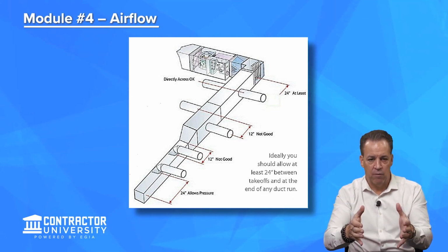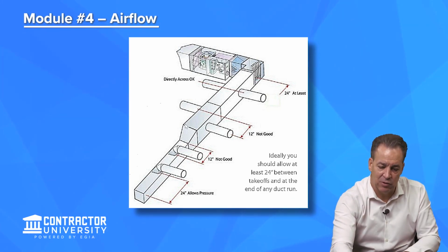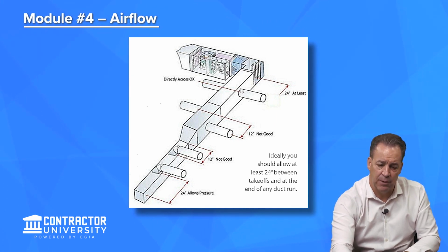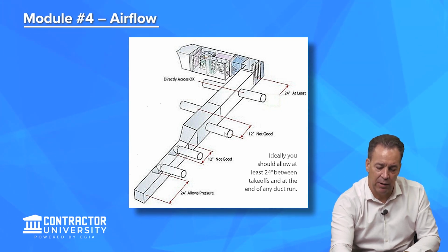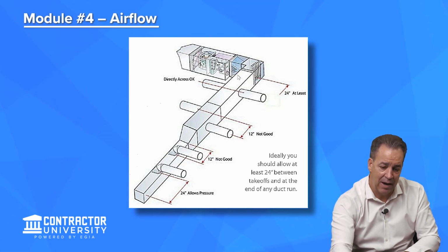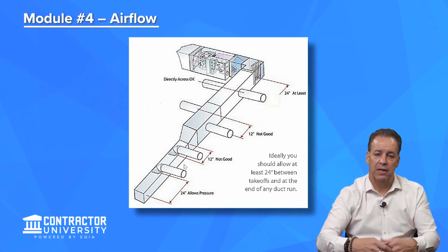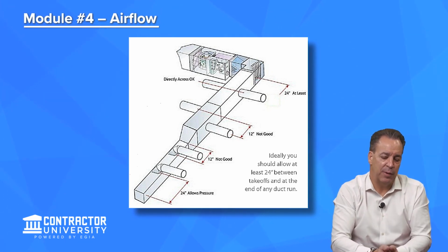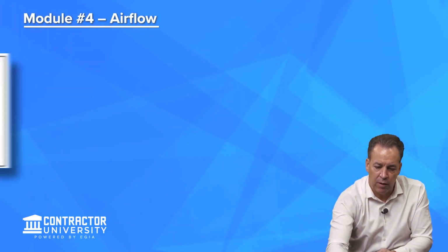We shrink the ductwork for the amount of air that's now left, because let's assume we had 1,200 cubic feet of air going in here on a 3-ton machine. We have 100 going out here, 100 going out here, 100 going out here, and let's say 200 going out here. So that's 100, 200, 300, 500 came out of this ductwork. So I shrink this down, so this ductwork carries 700, and then each of these gets what's left. And so that's the principles behind designing ductwork.